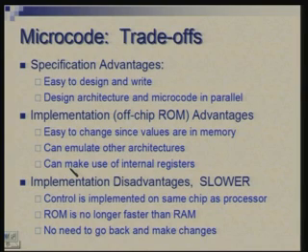In the past it was thought that the processor could be one chip which will have the data path, but the control could be moved out into a separate memory chip which is ROM, and you could change that. So suppose you want to make a change in your processor design, want to add a few instructions, you could simply modify just the contents of this memory, and the rest could remain the same. In fact, several times the families of processors were designed like this, that you would have different microprogram implementation, although the data path may be the same.